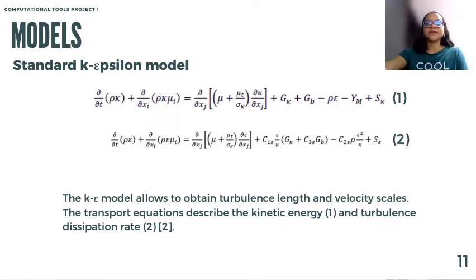Only one turbulence model was used because the model suggested for mineral oil, despite being more efficient when calculating turbulence in flows with high viscosity, is not very good at modeling systems with high Reynolds numbers and relatively thin meshes, which is our case. Furthermore, it was simulated with both models, and the efficiency and absolute pressure in both simulations were very similar, which means that the mineral oil in our system does not have a very different behavior at the boundary compared to the rest of the pump.